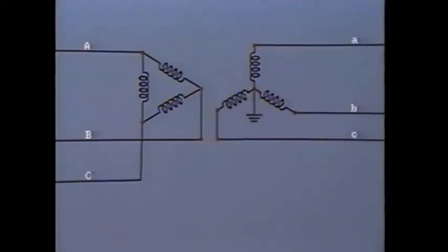If a 3-phase short circuit occurs downstream of the secondary, heavy fault current will flow through all 3 phases of the primary winding. In the case of a phase-to-phase fault on the secondary, in this example between lines B and C, then heavy fault current will circulate in the secondary B and C phase windings, and likewise, heavy current will flow through the associated windings on the primary.